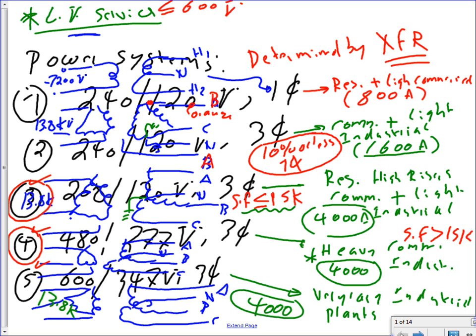You know where we use it typically, right? Let's go to system number two. System number two, I'm putting in the typical voltages that Xcel or other utilities will give you: 13,800 volt on the primary side. On the secondary side, you have a 120/240 three-phase. This system is a three-phase system. Can you see the difference between this single-phase system and this 120/240 three-phase system?